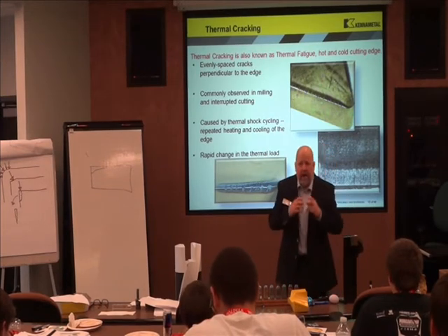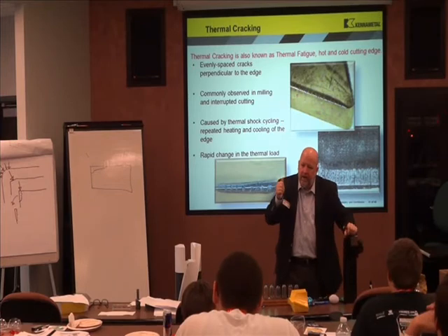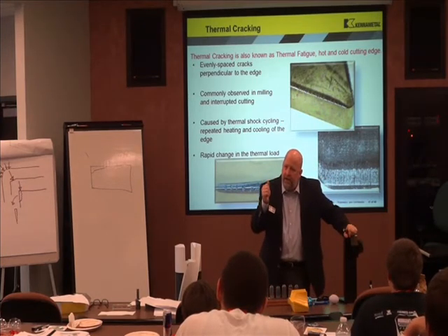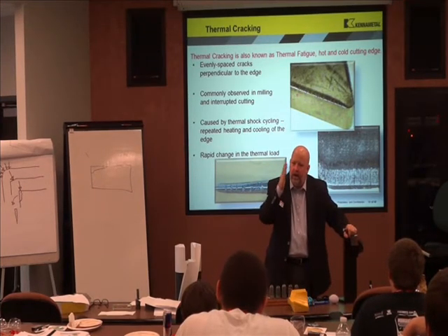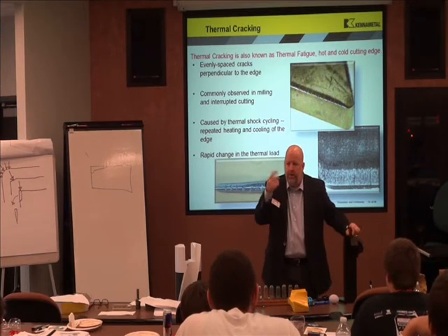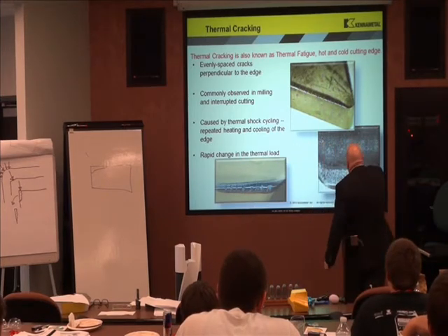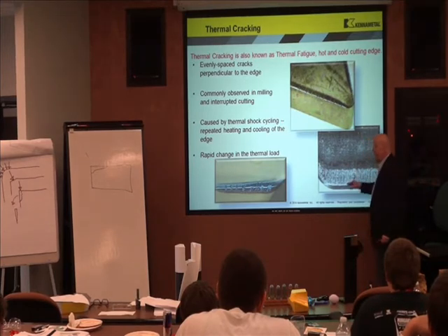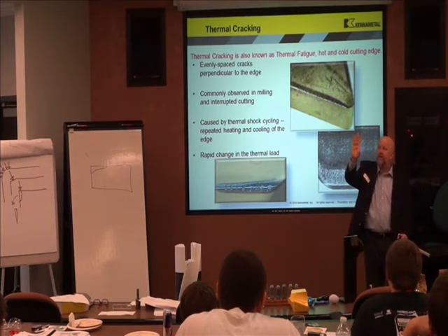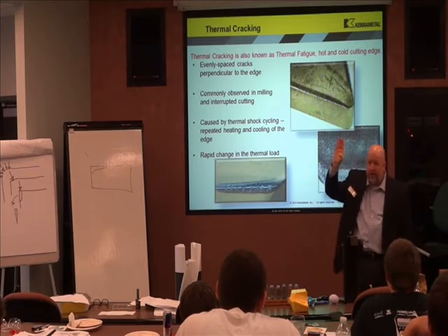When things heat up, what happens? When they cool down, what happens? In milling, your insert is already heating up, cooling down. It's getting hot, cold, hot, cold. It's growing, shrinking, growing, shrinking. You put coolant on it in between, what do you think you're going to do? You're going to shock it. You will actually get these cracks. They're called cone cracks. That constant expansion, contraction will literally rip the insert or the cutting edge apart.